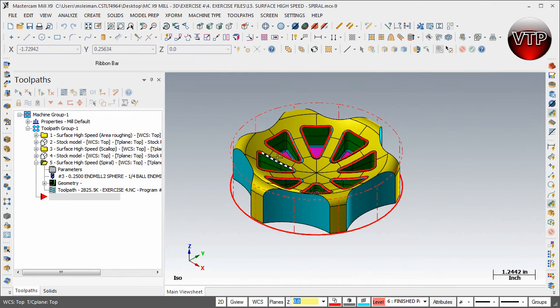For example, this pocket right here to this radius over here, that's all on an angle. So you can actually choose what area you want to machine depending on that angle, but they have to be between 30 and 90 degrees, which we do have in this little pocket. And I'll go ahead and get started so I can show you what I mean.